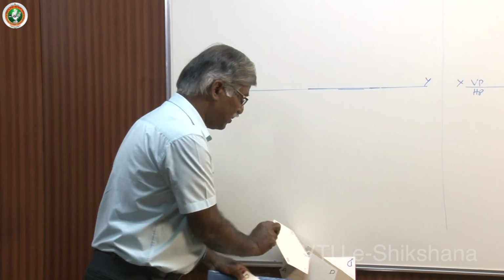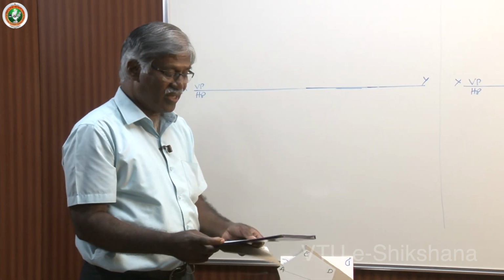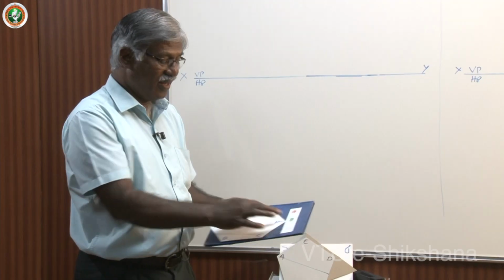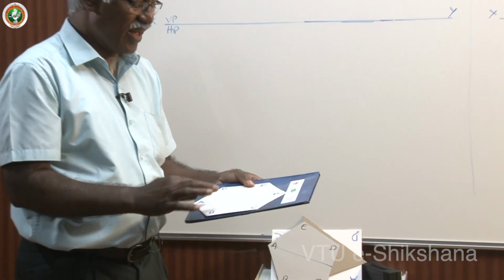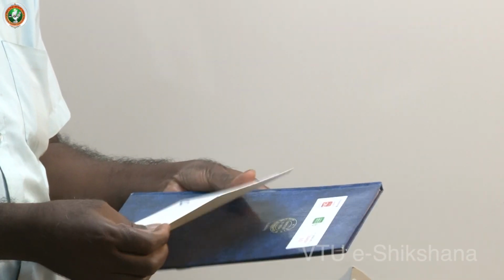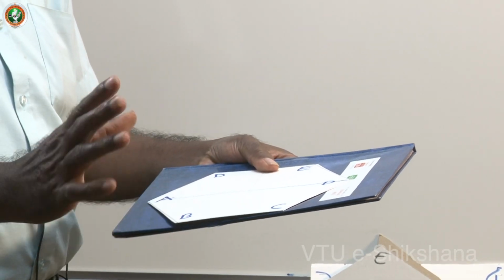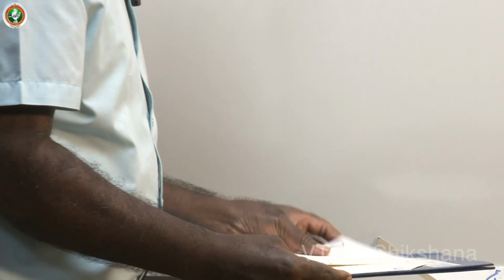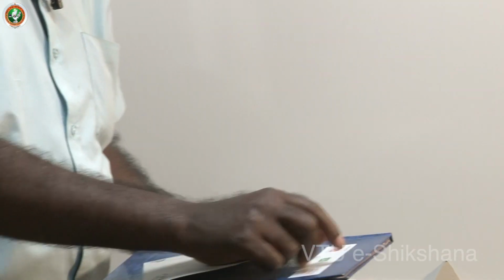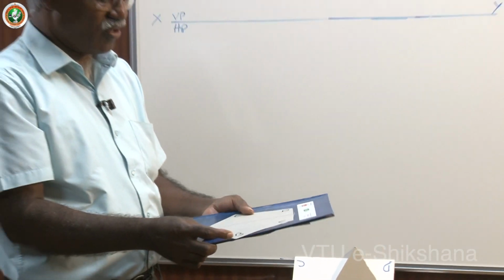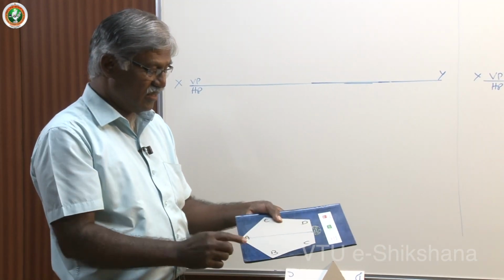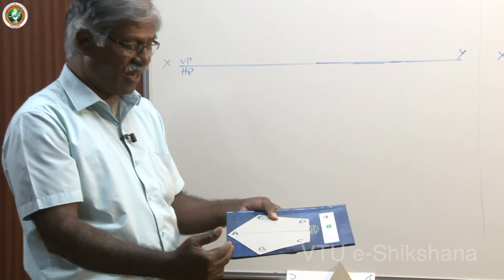For a hexagon also, same thing. The diagonal passing through the corner to be placed on HP is always parallel to VP. Then only you will get that corner condition. Then in case of an odd number of sides, say this is a pentagon. In case of a pentagon also, these two are making equal inclination with a perpendicular line to VP.